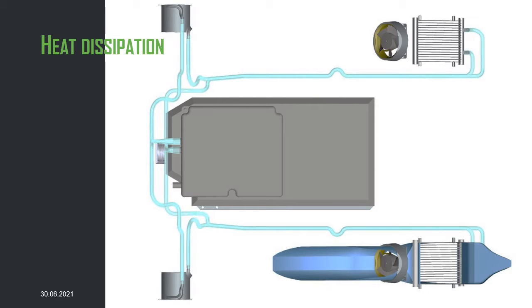In the center, the large grey block is the high voltage battery. It is air cooled and there are no water pipes going directly to the high voltage battery. On top of it is a smaller grey block, that is the inverter. It gets its water after it has passed through the motors, since the inverter is less temperature sensitive than the motors.